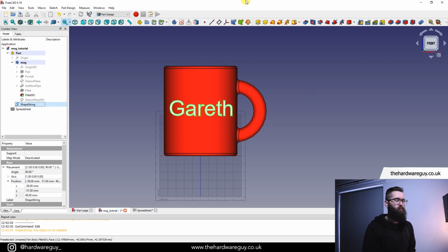So as I mentioned in the previous tutorial about text in FreeCAD, it's really not great. And in terms of constraints and parametric modeling, we can't really use that with text. The infrastructure for it just isn't there. We had to actually go and manually measure the text to position it. So we're not going to make use of parametric modeling for our text, just because you can't really.